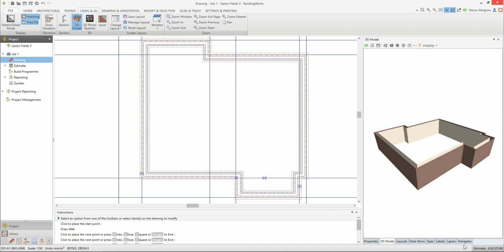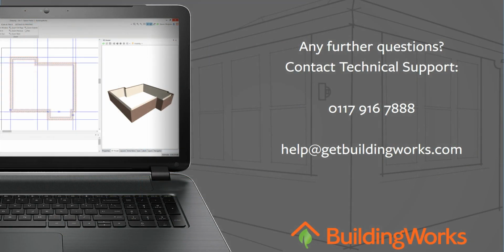Now it's your turn to draw your external walls. Select your wall type and use the Wall Component Builder to choose its specification and enter its dimensions. To draw the walls, locate the intersection points on the construction lines and click and release the left mouse button to place your corner points. Don't forget to check the justification of the walls and the external side, and also try out the C and S keys to complete your walls.